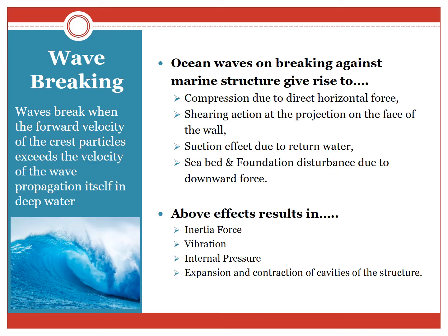Now let us move across to wave breaking. Waves break when the forward velocity of the crest particle exceeds the velocity of the wave propagation itself in deep water. When the wave height exceeds 1/7 of the wavelength, the wave normally breaks. Ocean waves on breaking against a marine structure give rise to the following effects. Now what are these effects?